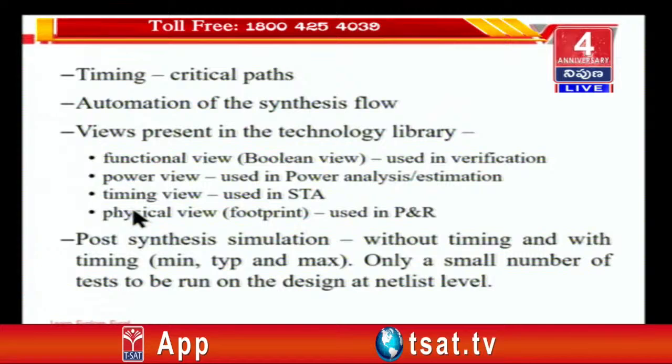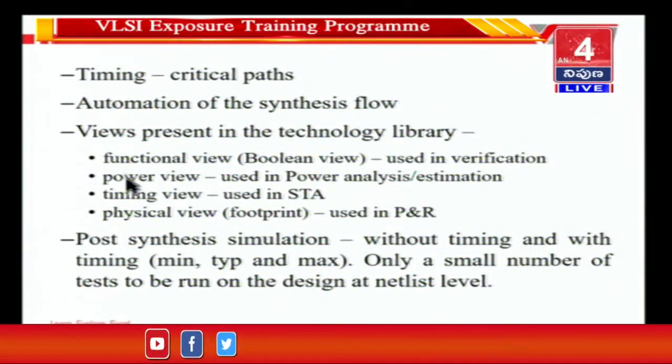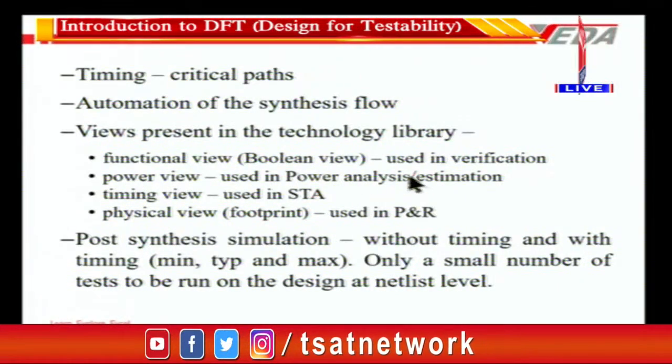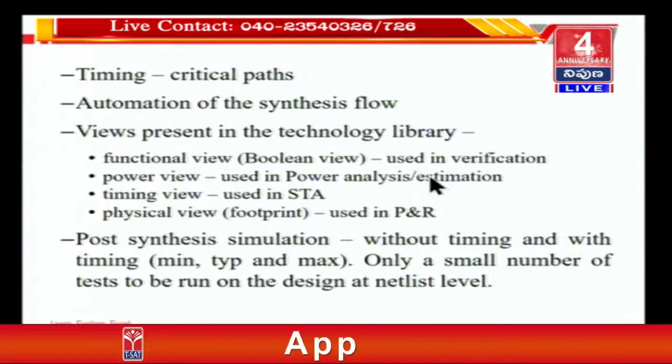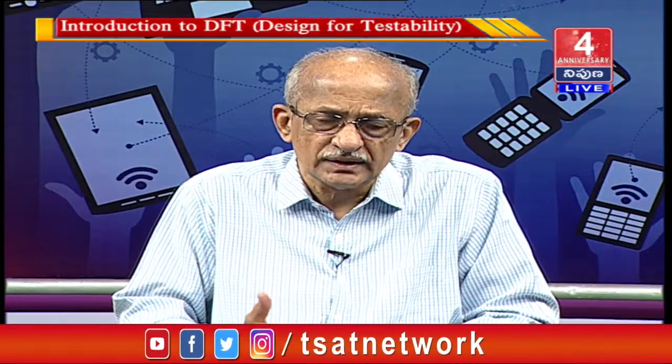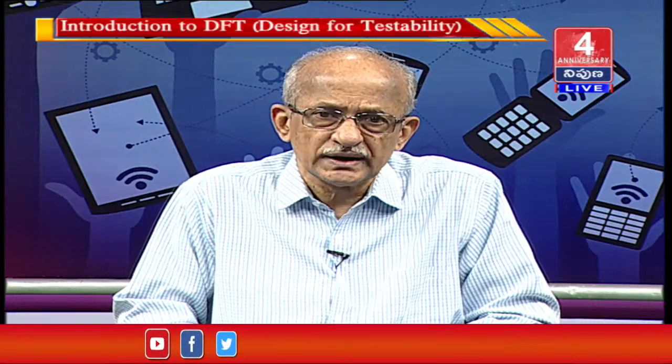This is not being written in any order of preference or priority, it is just randomly written there. So the power view is used in power analysis and estimation, to estimate how much power is going to be consumed by the particular circuit when it is working at a specified frequency. It is necessary to have some power estimation software also, and the power estimation software will make use of the information given for each and every cell of the technology library as to what amount of power is going to get dissipated.